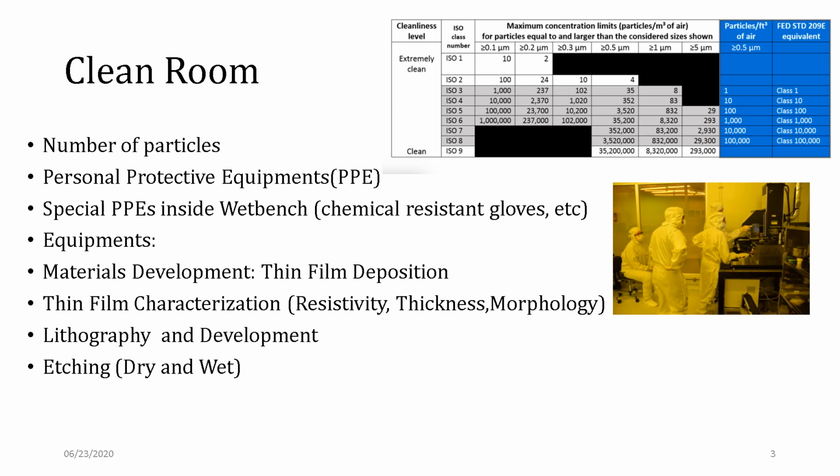And after that, suppose you are developing thin film structures like cantilevers or beams, and you need them for a particular reason, and they should have a particular thickness. And you need to make sure whether your process has given that particular thickness or not. Especially after processes like etching, you need to check whether your material is still there or not. So you need to measure thickness. And similarly, you also need to look at the patterns optically, to check not the morphology per se, but at least features.